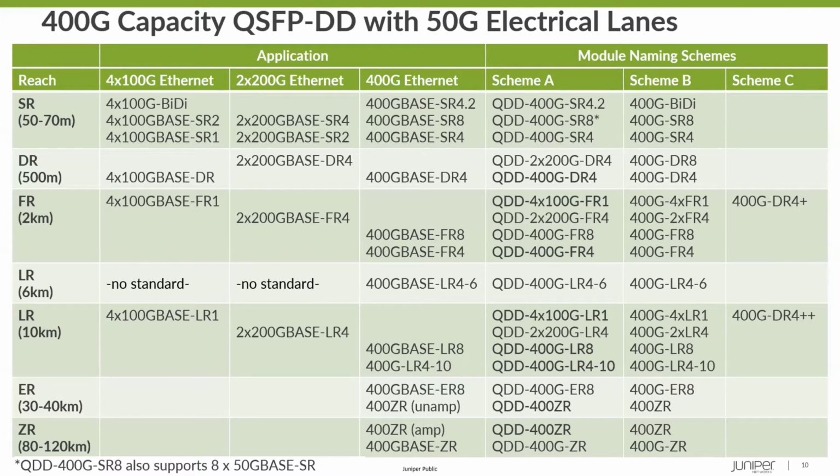Now above that is the 400 gig DR4, which is a 400G based DR4, IEEE specification. And that's this famous module now that also does two things, 400 gig and quad ports of 100 gig Ethernet with the 500 meter data center reach. Of course, there are other applications that only, a module only does one thing, such as down at the bottom with the new coherent 400 ZR spec coming out of the OIF.